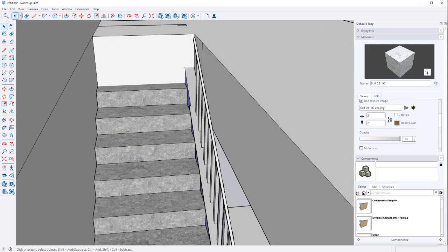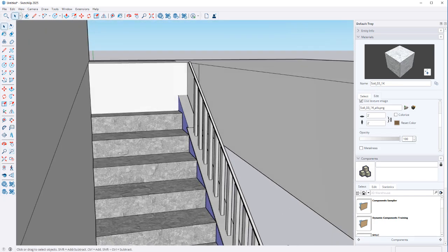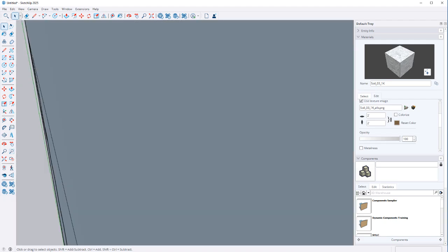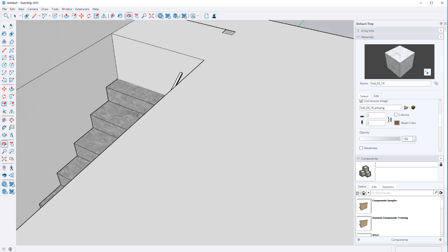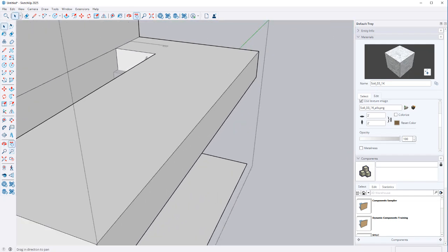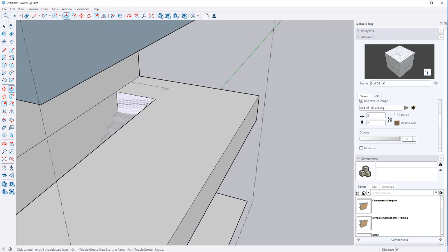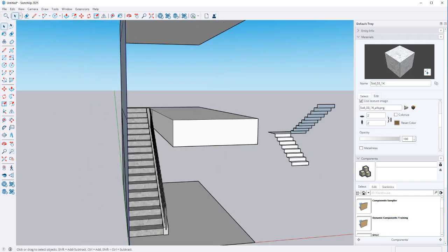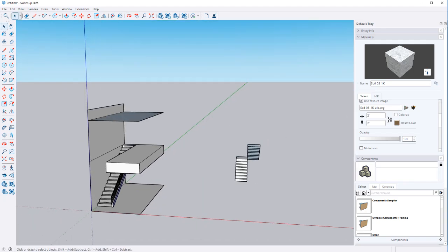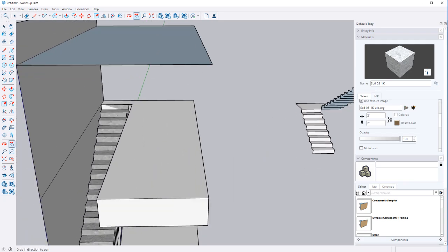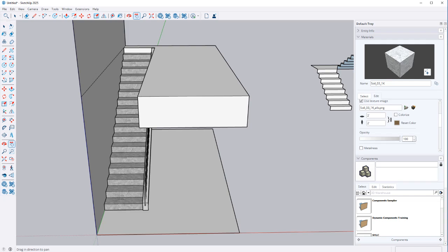And again, you can see that I've still got this railing here, but once you get to this point, this is where you'd want to switch to having it attached to the wall. But you'd also want to have it continue functioning as a railing through that transition. Your wall side, again, is a little bit simpler if you attach it to the wall. And then once you get into dealing with one of these staircases, that's when you get into a modeling nightmare. It can be done. It's just going to take time.